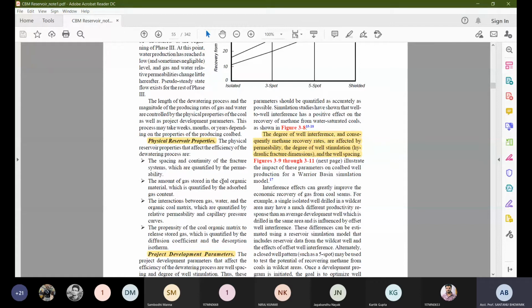So with that differential property, how are they going to move into the fracture system? Now imagine that there is an oil part, there is a gas particle, there is a water particle. The particle size, the diameter of the particle can vary. The viscosity of this gas and water when moving will also vary.